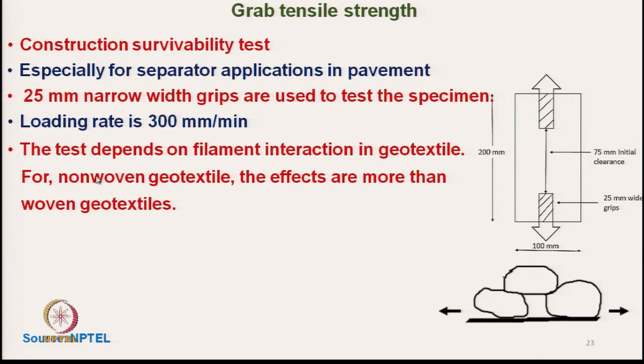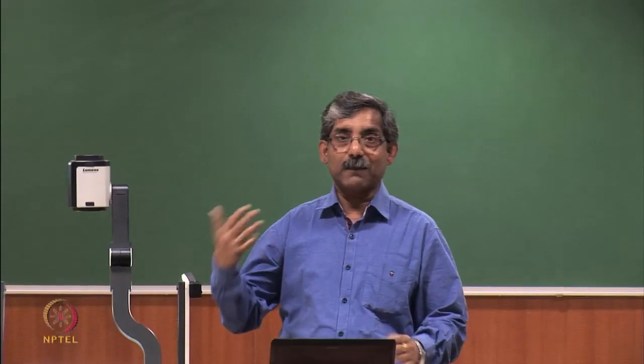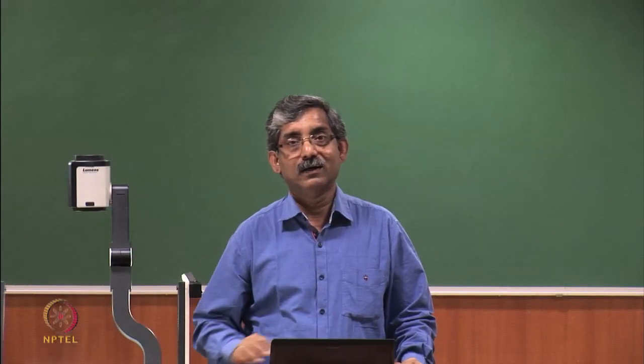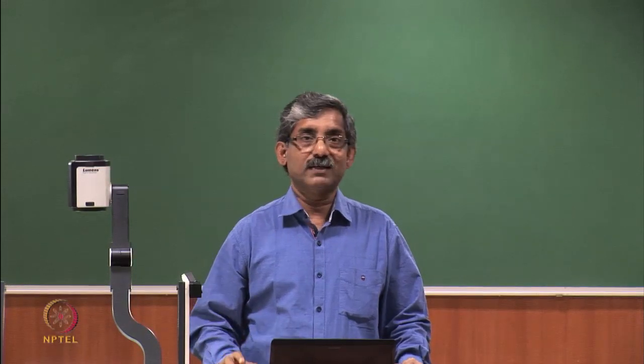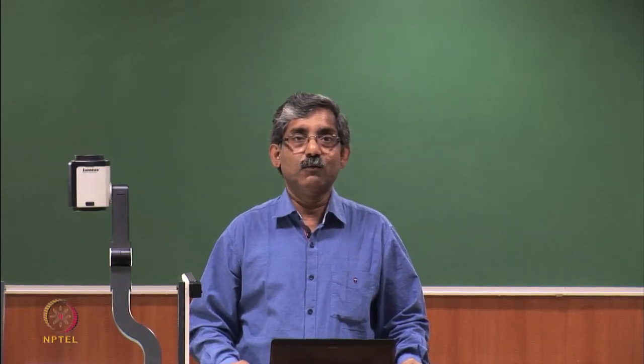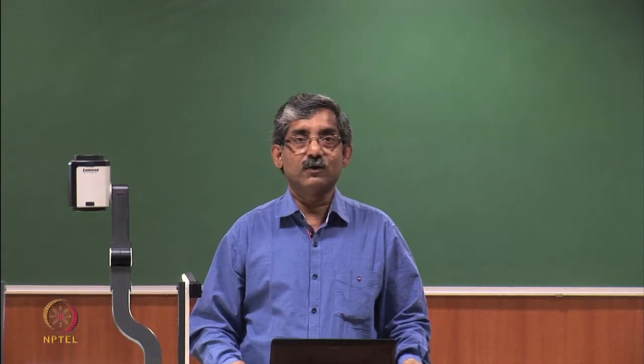The test depends on filament interaction in geotextile. For non-woven geotextile, the effects are more than woven geotextile. So, if we compare the Grab test and the strip test, the effect will be more in case of non-woven geotextiles.